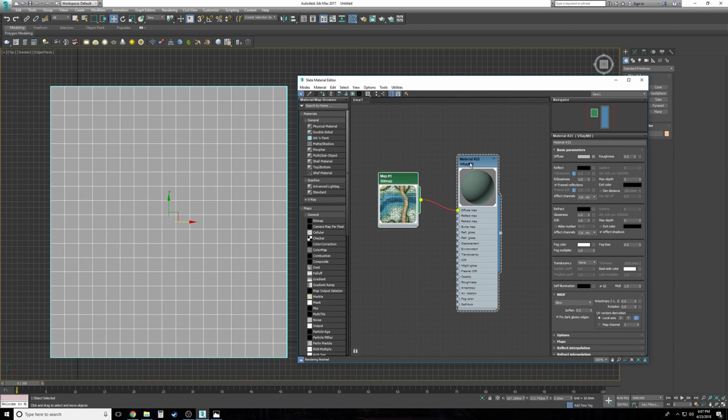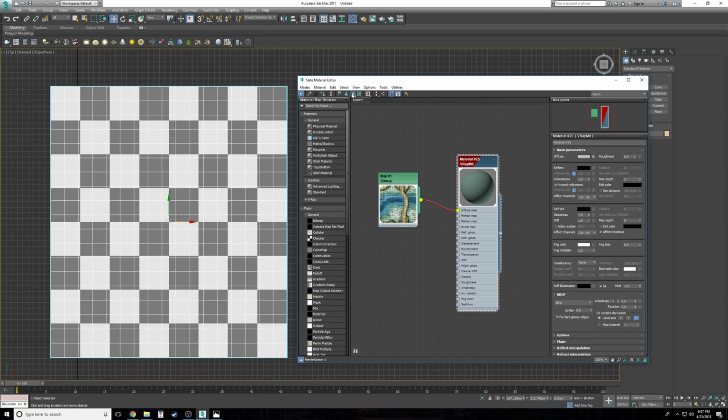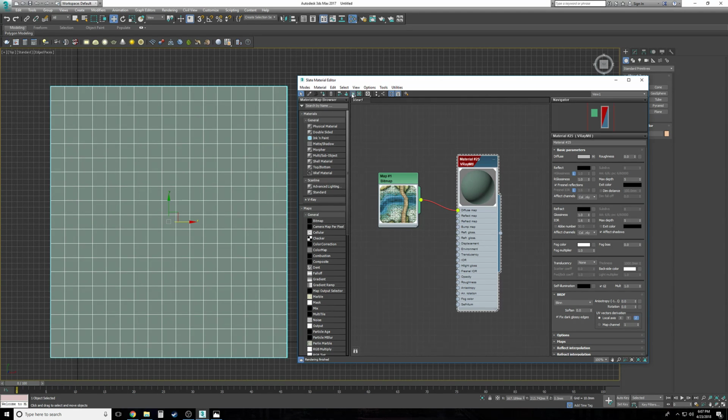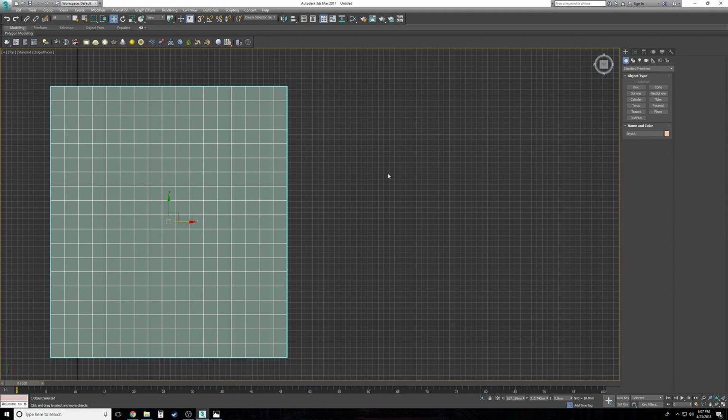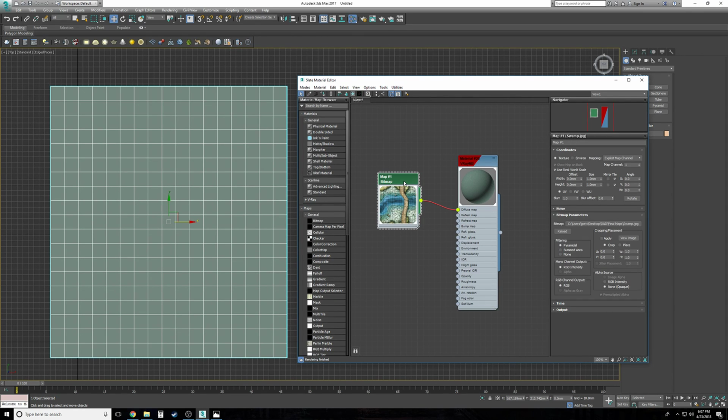Why? Well, what you've got to do is select your material, and then there's this hidden little button here that should be on by default, but it isn't. It says show shaded material in viewport. You click it, and it comes out. Oh, still does not show anything. All it does is show this weird kind of green look to it. Well, you can close out that because right now, maybe not. Let me do one more thing first. Because one of the things is it has this use real world scale, which you don't need. You turn that off.